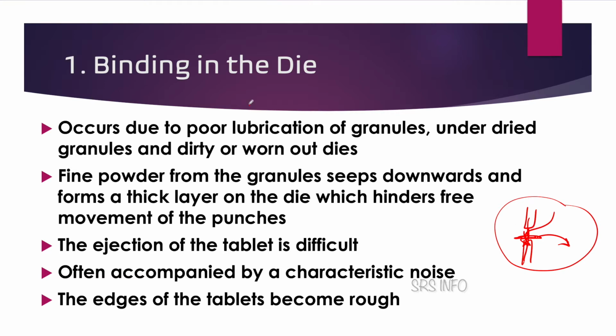And what is meant by binding in the die? The sticking or binding of the granules on the die. And this occurs due to poor lubrication of granules or under dried granules and dirty or worn out dies. These are the main reasons why binding in the die occurs. Maybe the granules are not properly lubricated or are extremely dried. Otherwise, there is a possibility of the usage of worn out dies.